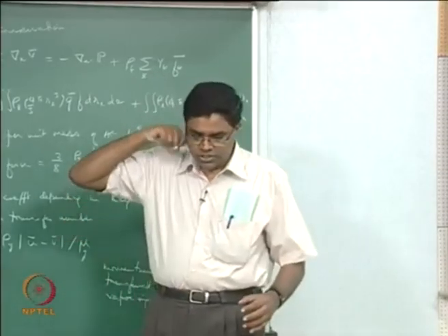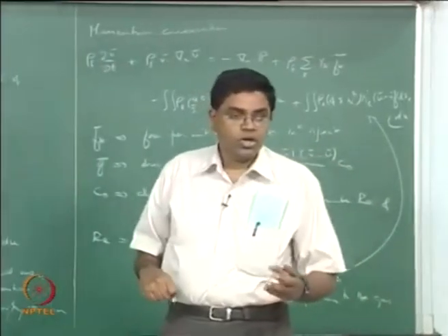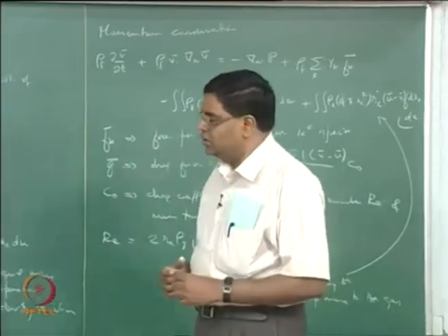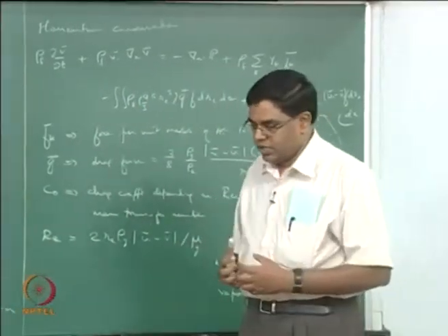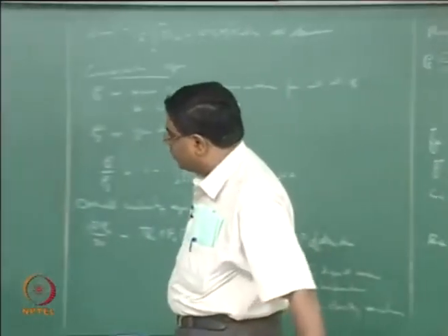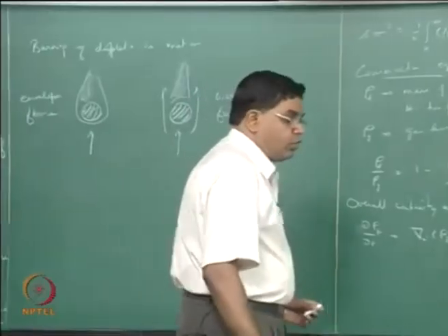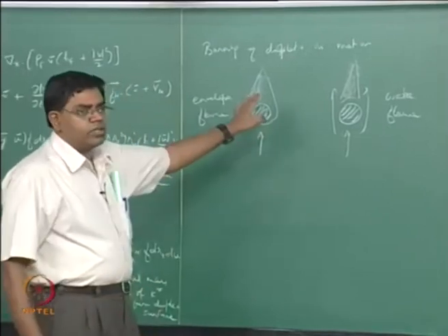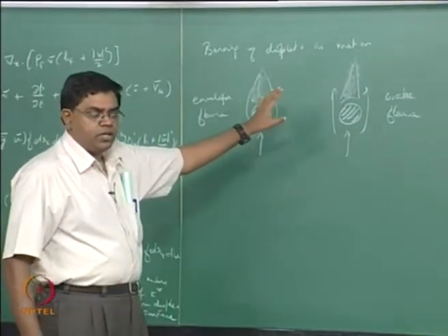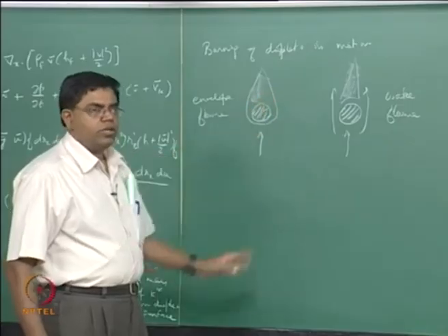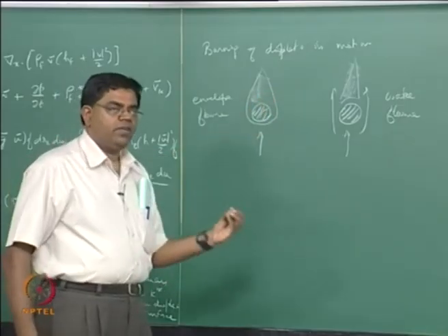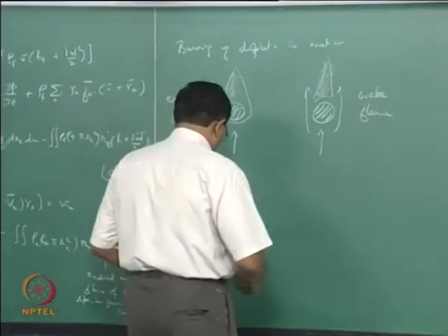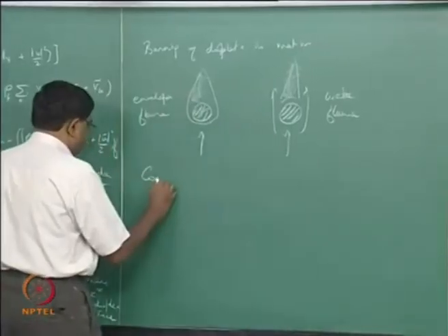And yesterday we mentioned the situation of, let's say, coal combustion, where you have single particle combustion rather than a cloud combustion. That is because of lesser volatiles. So I'll just quickly talk about coal combustion and other solid combustion. We also mentioned, for example, metal combustion, where it is similar to droplet combustion, because by the time the metals are actually burning, they melt, and so you have molten metal droplets that are burning. Although it may seem like we are burning solids, in reality you might end up burning liquids. So if you now think about coal particles,